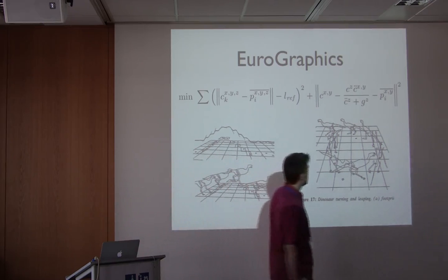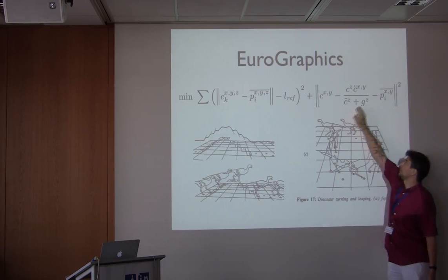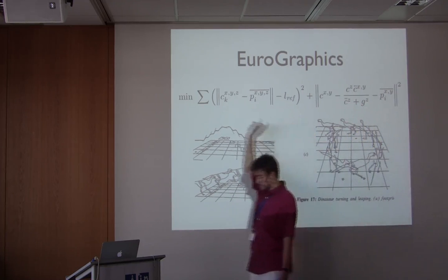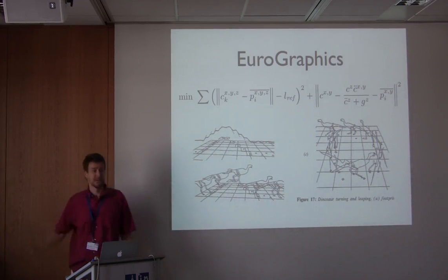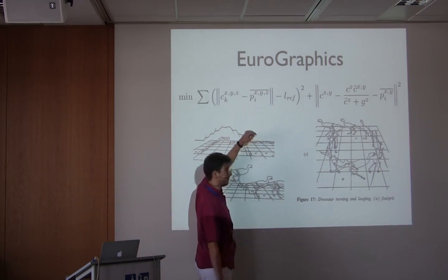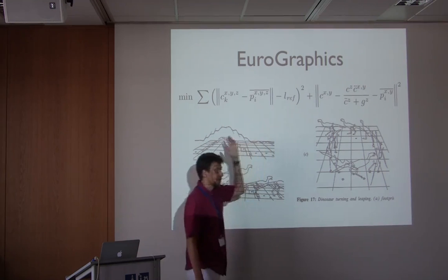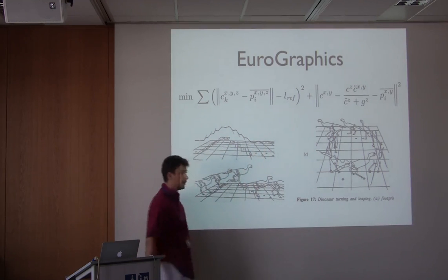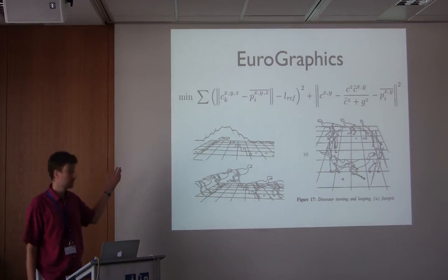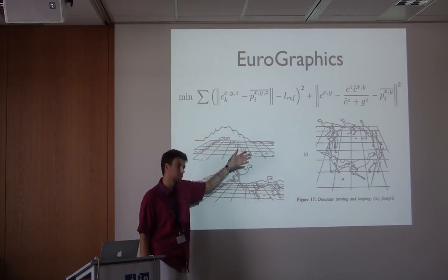The striking thing here is that what he imposes is that the center of pressure is close to the center of the feet. Okay, fair enough. But here he doesn't minimize the derivative of the motion of the center of mass. What he does is in fact keep the leg length, the distance between the center of mass and the center of the foot, rather constant, because he was generating 3D motion. So here there was nothing related to the stability analysis that I proposed. And yet, it worked. You can see here, the plan is always changing, but in the end it works.